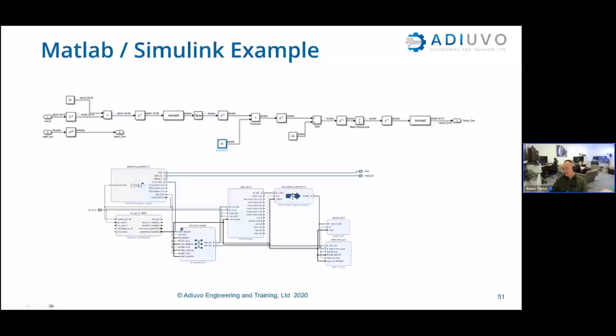So we calculate that temperature by running through again. I do some registering, and then we do some maths in the chain. So we do some conversion from a fixed point to a floating point. We do the logarithms, the inversions, and then we finally convert back to a fixed point system at the fixed point output at the end.